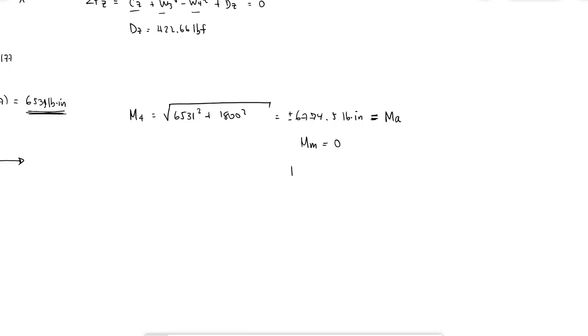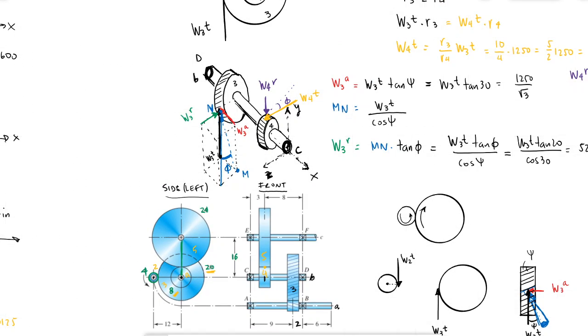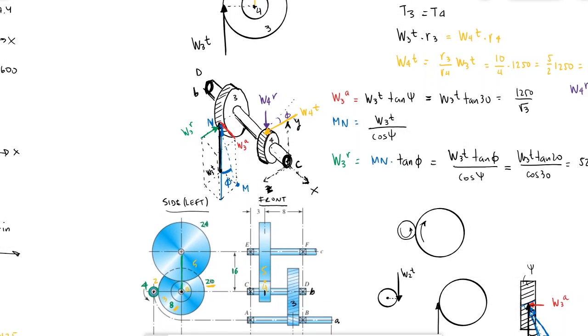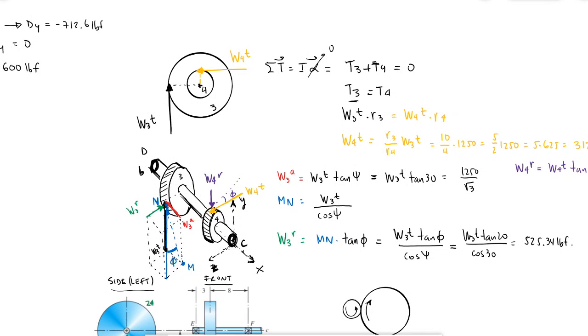But also, I have that the alternating torque is 0, because it's not alternating, it's a constant torque. Shaft B is under the torques that I had already calculated here. Okay, T3 and T4 are equal and in opposite direction, so the torque inside shaft B is either one of these. Okay, so let's do R3, which was the 10 here.